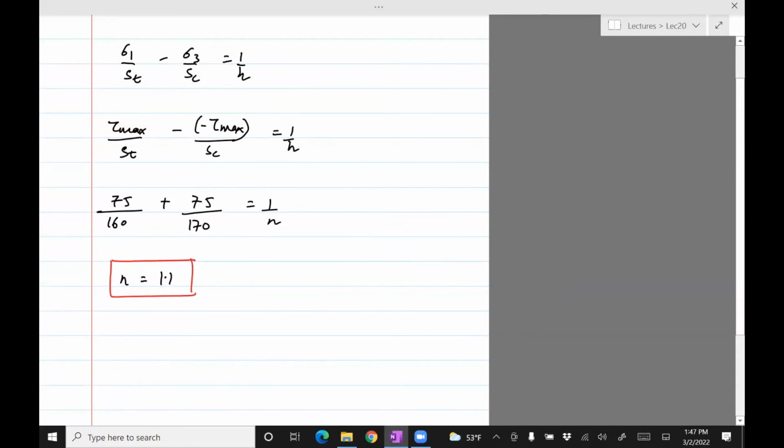Okay, if the factor of safety was less than 1, that means that element will fail, because it's saying that the stress is going to be more than the yield strength. But 1.1 is fine. You normally don't have something which is 1.1. You keep a factor like 2 or something like that. 2 is for lightweight structures like aircraft, where you're transporting things, much higher for ground vehicles and much higher for bridges and elements which are on the ground like buildings.